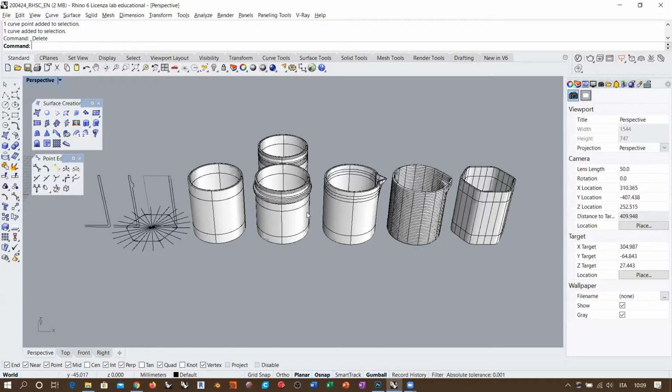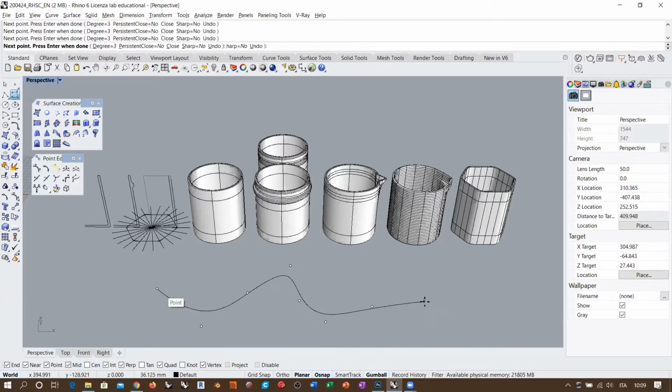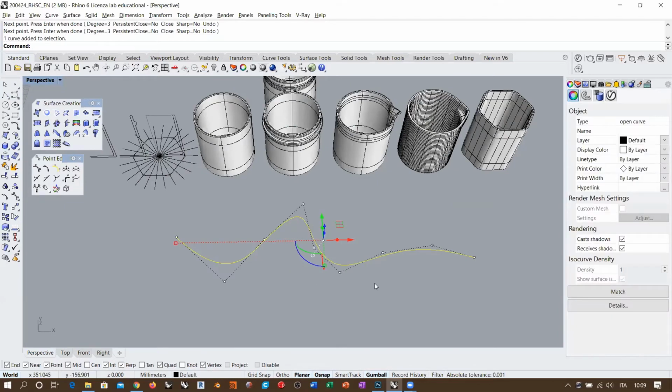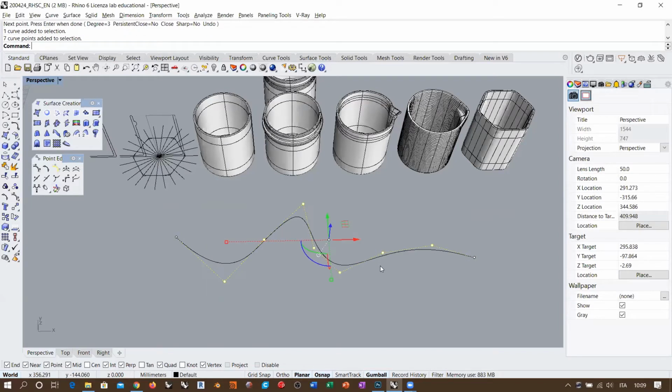Because if you think about the standard NURBS curves or surfaces that you create with Rhino, let's do this with a curve, but it's the same if you do it with a surface. This degree 3 curve, as it has by default a uniform knot vector, won't have any internal kink. So by default, you cannot create an internal kink with Rhino directly. You can add a kink later on, but you cannot create it directly. You can do this with Grasshopper, but not with Rhino.